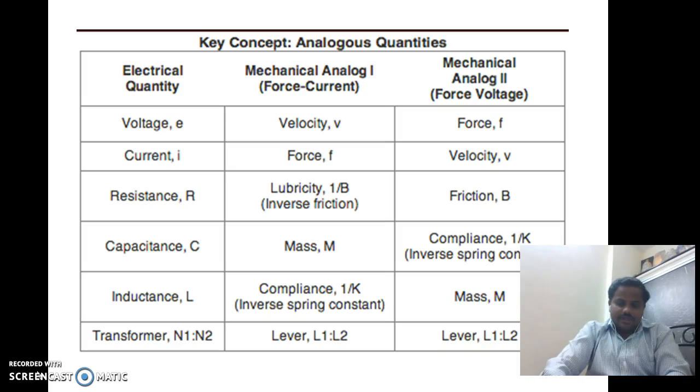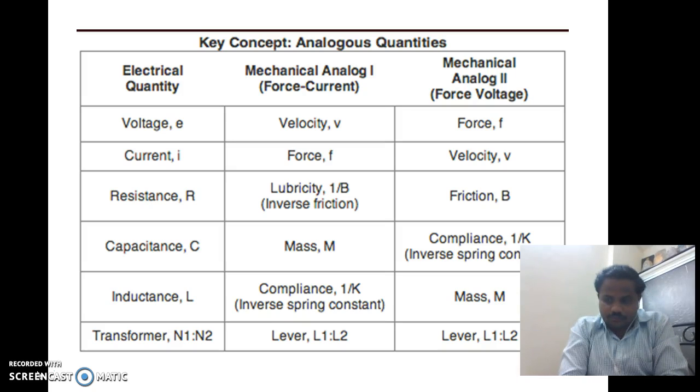Due to that, they are named force voltage analogy and force current analogy. In force voltage analogy, the force in the mechanical system and the voltage in the electrical system are analogous, and in force current analogy, force is analogous to current.